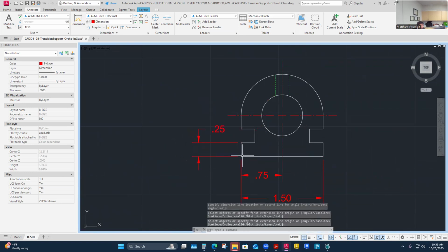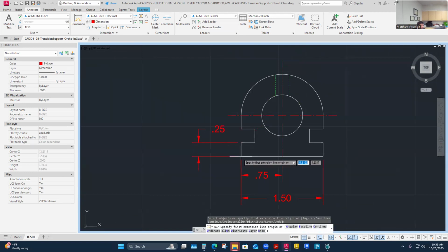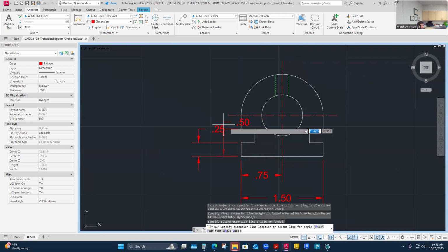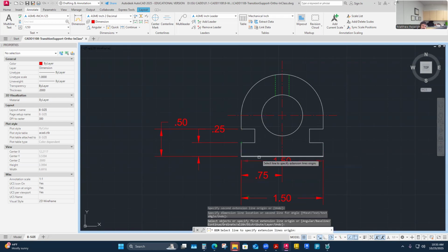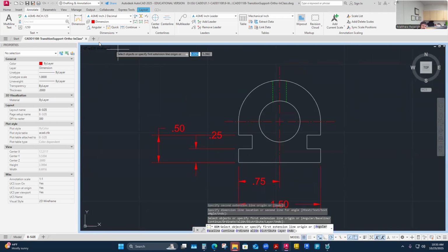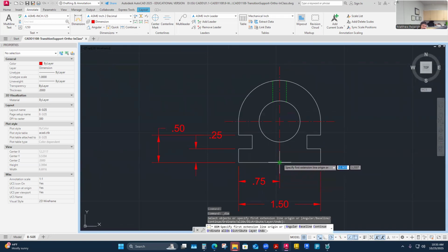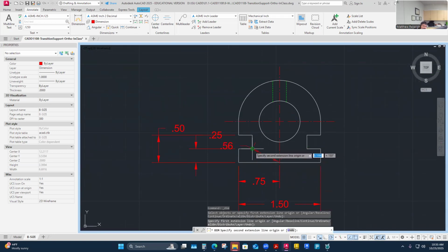But then I'm also going to say to the next, from the same datum here up to this, rather than say from there to there, quarter, I'm actually going to prefer this pulled from the same base. And then I need the depth of slot here. And that's going to maybe break some rules. So I think I'll pull it from here though. This is a datum to here.